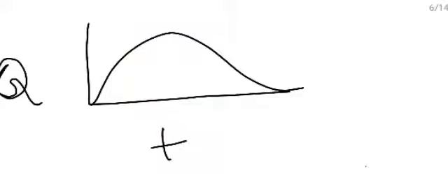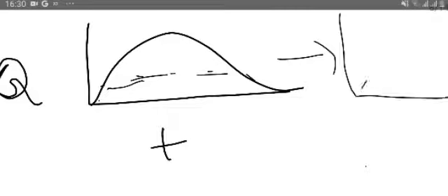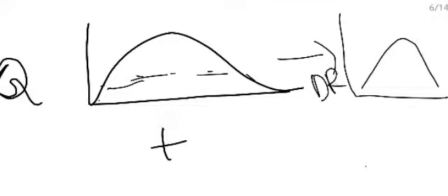Now one more thing you have to notice, the initial surface runoff will be that water already stored in the depression. So we call it base flow. You have to subtract base flow as well from this, and after subtracting this base flow you will be getting the direct runoff hydrograph.